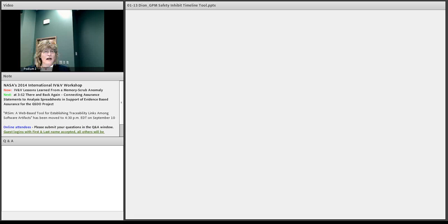Okay, and the last definition is designed for minimum risk. This is the method by which structural members, pressure vessels, pressure lines, pyrotechnics, material capability, mechanisms, where fault-tolerant design is not practically possible, shall be controlled by design standards and so forth. I'll point out that under that umbrella is safe by design. There are situations when you need to contain a hazard, and so you can't count fault tolerance quite the same way. One example would be an arming plug. When you remove an arming plug, you're safe by design because the continuity of the circuit has been removed.